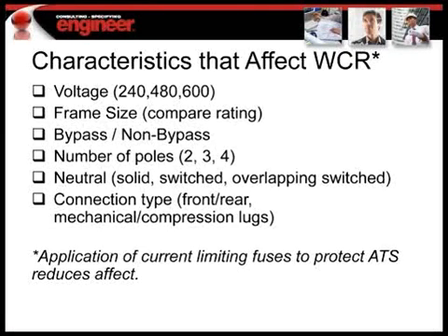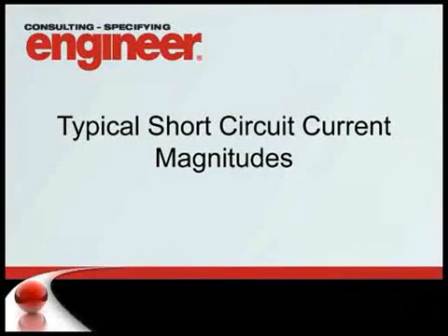Whether the switch uses solid or overlapping neutral contacts also influences the withstand and close-in ratings. And then the type of connection to the switch, whether it's front-mounted, front and rear accessible, or top connection, affects the withstand and close-in rating. So when you're specifying transfer switches, you need to identify all of these parameters either in your specs or on the single line diagram.